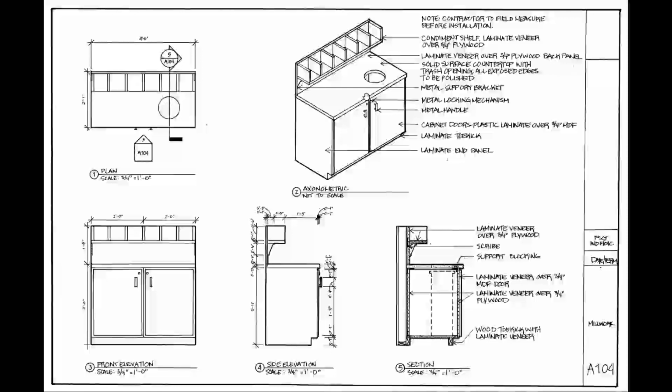So when I did this, I moved up. I used actually the thinnest thickness, so the 0.25 millimeter was where I started, for the very, very, very thin lines and the tiny little objects. And then where I could move up a little bit to differentiate and to give a sense of hierarchy and to do the change of plane that were a little bit thicker, that's where I used the 0.3 millimeter.